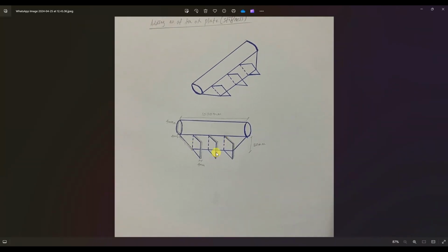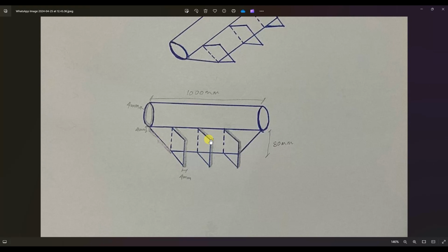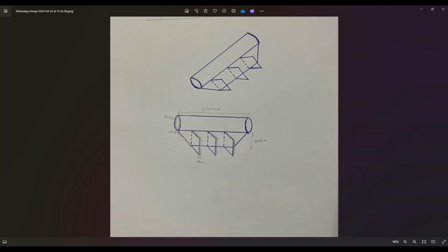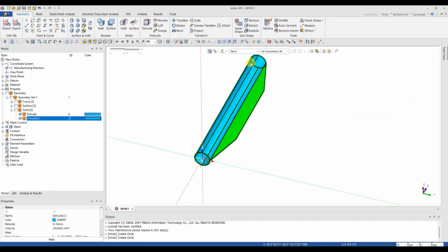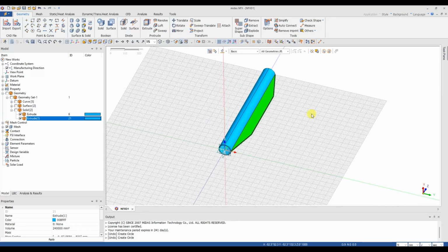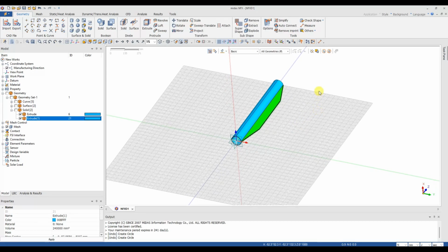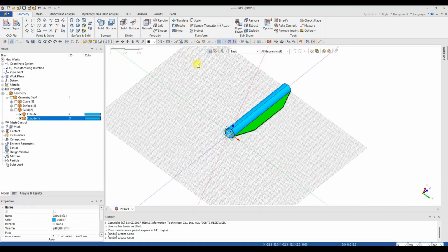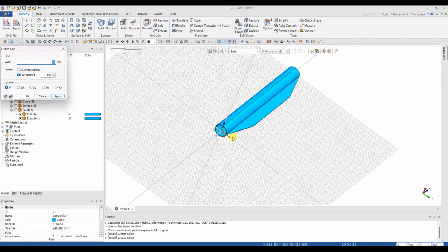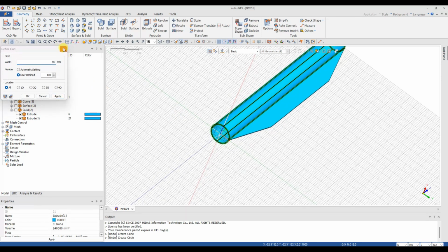All right. So I'm going to create this square model or square part. Once it has been created, I'm going to duplicate it by transferring the distance from this one to this point, and I'm going to duplicate it to the other side as well. Okay, so before I do anything on that, I just make sure that my working plane is properly sitting on the desired location. So in this case, I'm going to move my working plane to somewhere here, sorry.